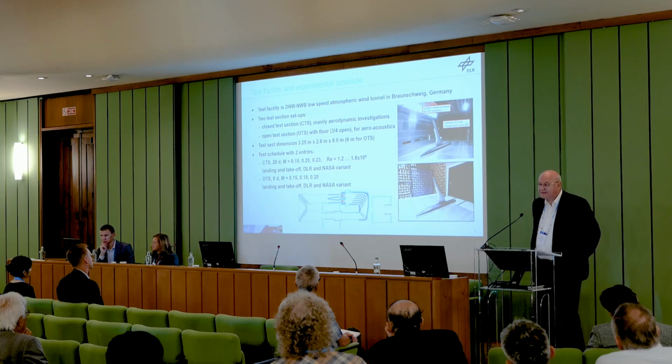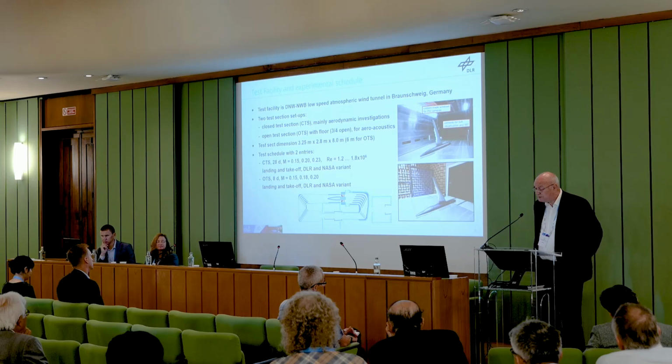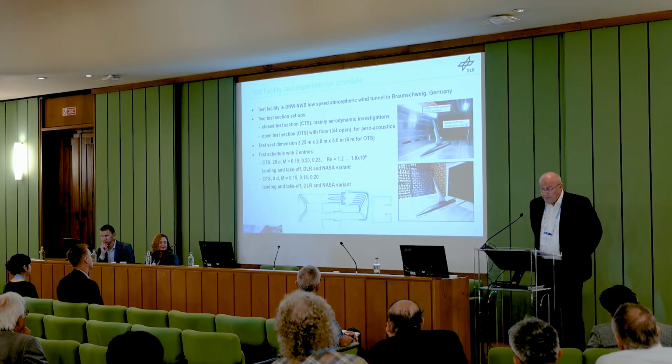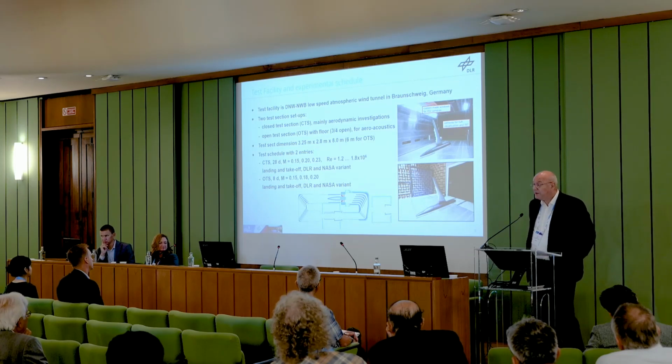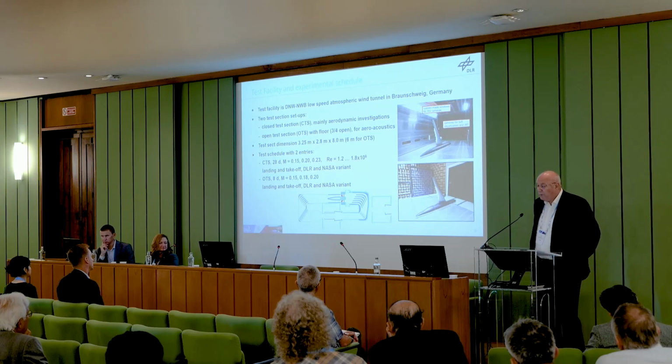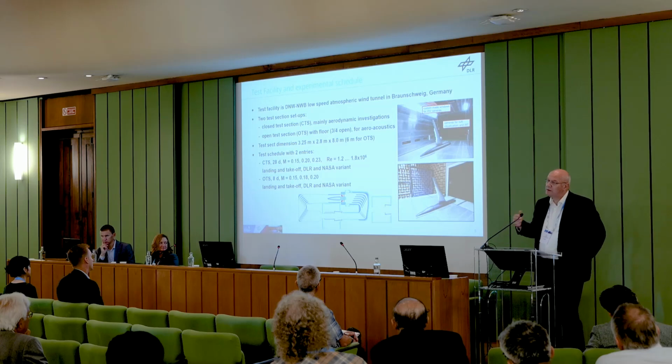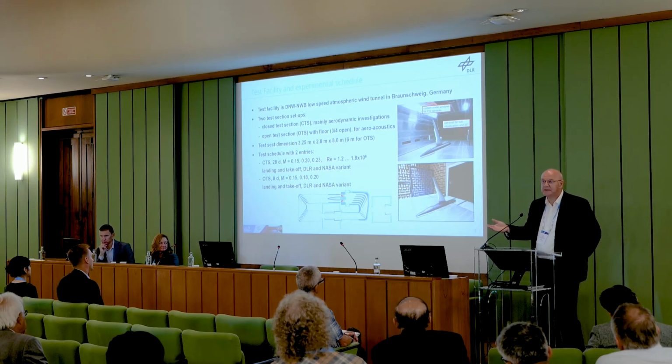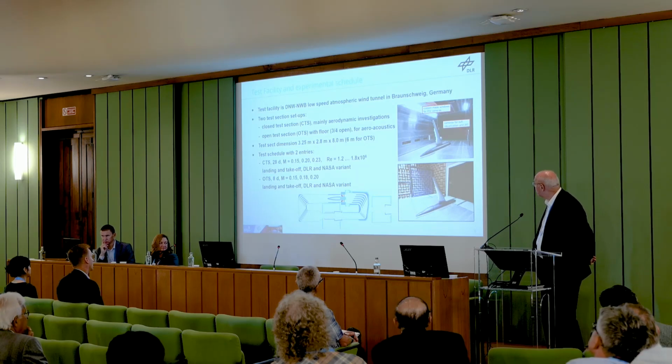The test section setups that we looked at have been two. The closed test section, which you see in the upper picture. Test section dimensions are listed down there. But we also intended to look at the open test section. Usually you go for a closed test section for aerodynamic testing and the open section for acoustic testing.